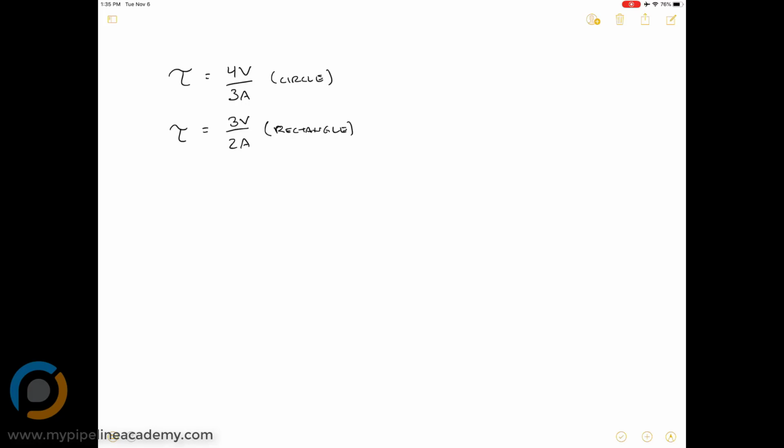So, going back to shear stress, just like bending stress or stress in tension, the reason that you might want to calculate shear stress is to compare it against your shear yield strength and determine whether or not you're going to have a failure in shear.